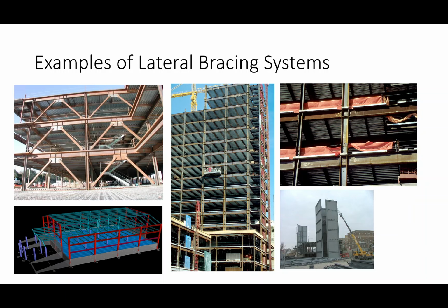Of the common ways that we resist lateral load, the two most common are brace frames and moment frames. To give you a CE 312 equivalent, a brace frame is basically a truss. We literally stick a truss inside the building at key locations. And talking about architecture, there are limits as to where we can place that.